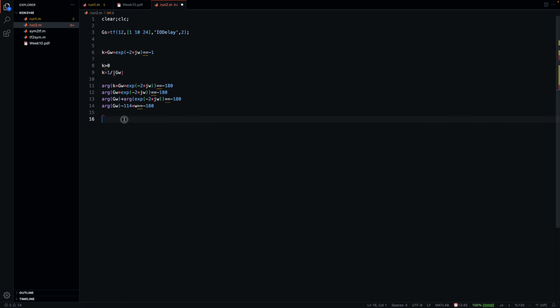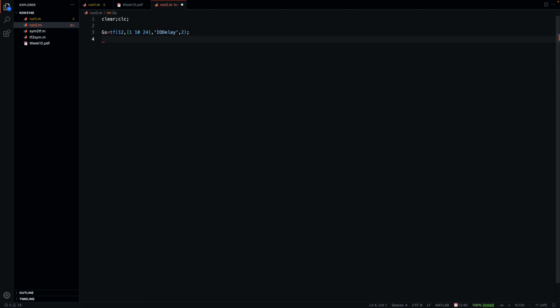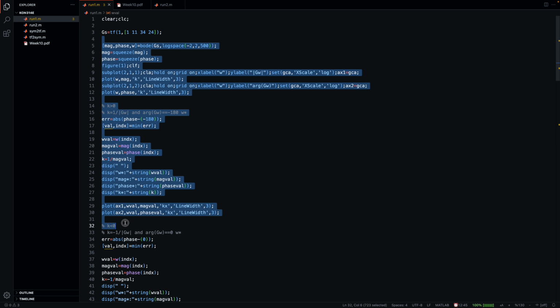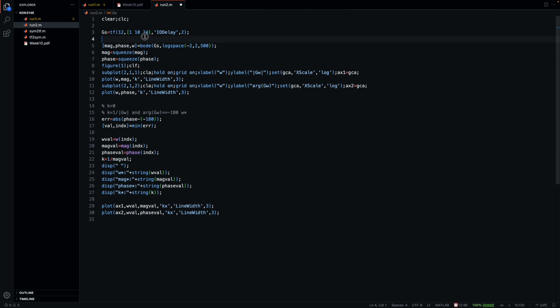That's basically it. Now, when we plot this, we can just directly use the Bode plot here. And I'm also going to get this up to this point here, maybe, because it doesn't really matter if we have a system with delay or without delay. We will just use bode, and we can calculate the Bode plot. We know for a fact that the gain plot will not be different than this portion here. If we have delay or not, it doesn't change, but the phase plot will change drastically, and we'll see that in a minute.